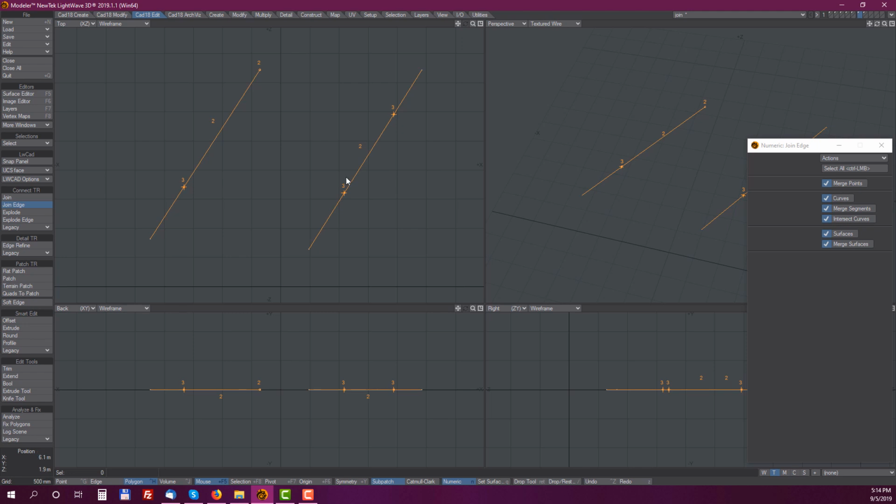You can see these 2 and these 2, and the result is a clean polyline. So there are no hidden or overlapping line segments. This is really helpful if you have a messy floor plan. This option removes a lot of hidden problems without the necessity to do it manually.